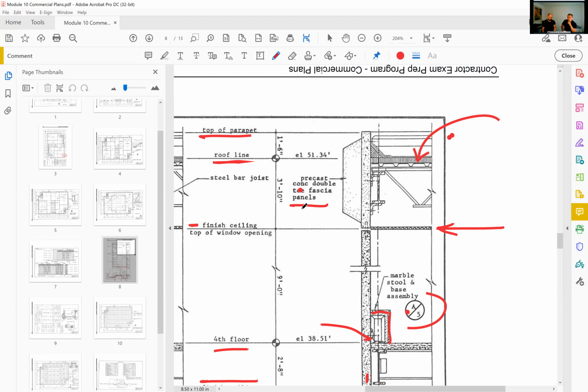But looking inwards, we have this exterior panel, then another wide flange, and then this guy here is a bar joist. Now this is kind of interesting because they're using a different structural system and assembly for the roof. Instead of a concrete slab like on the other floors, this one uses a bar joist, which is like when you go to Home Depot and look up in the ceiling, it's that zigzag kind of thing. It's a steel bar joist.